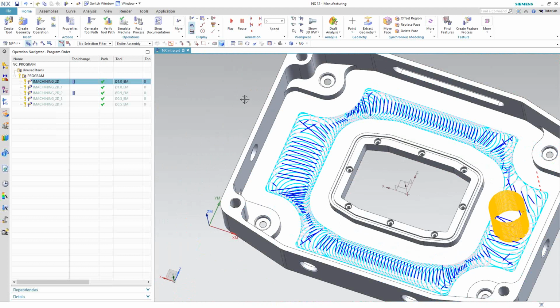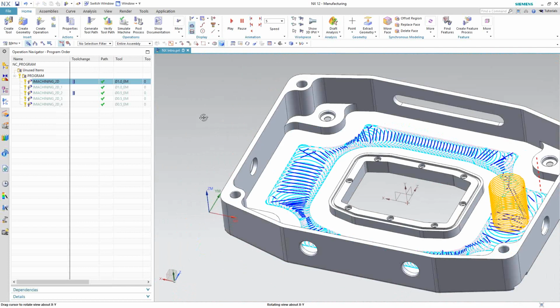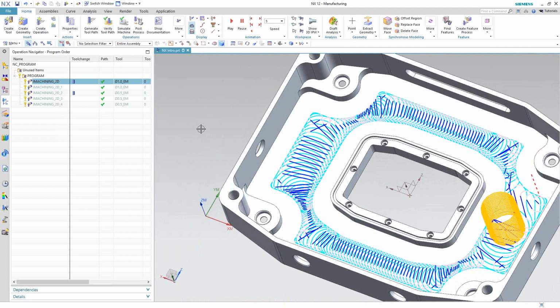As it gets closer to a corner, you can see that it's actually working its way into that corner as well. So that is the third aspect of iMachining, what we call the D-slot trochoidal. A lot of this is to maintain material engagement, but maintaining the chip load at the same time. So we're not overworking the tool, we're extending the tool's life. At the same time, this trochoidal toolpath, the iMachining toolpath, reduces the cycle time. So it is a very optimized toolpath, as you can see here.